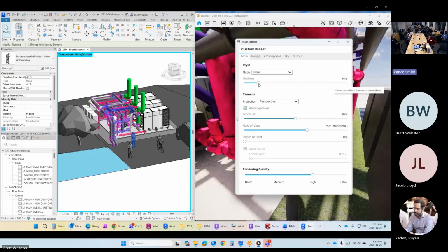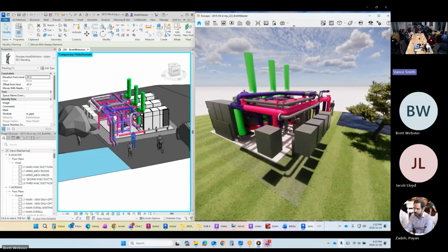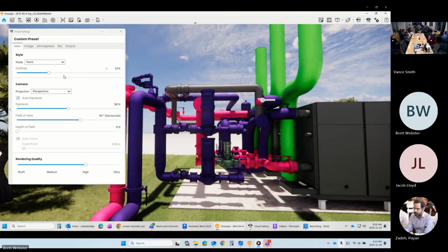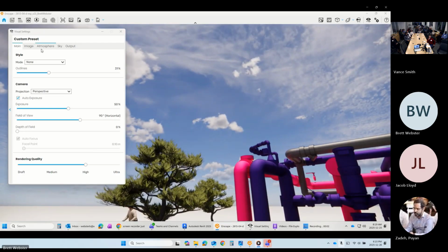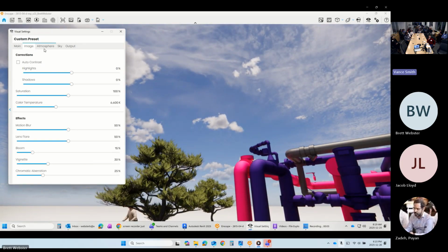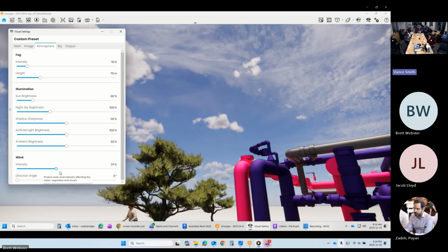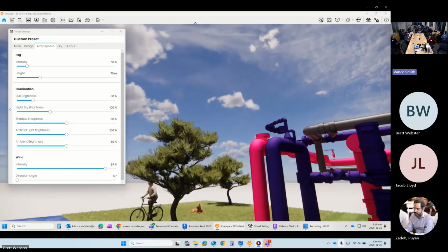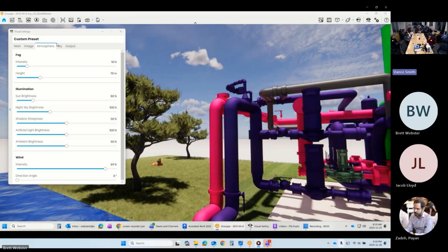So that's one of the atmospheric settings that you can do. Just scroll around in a second. Then you can look at the rest of your environment as well. So it's just going to flick over in a sec. The rest of the environment can also be controlled. There's all kinds of camera settings, image settings, but the atmosphere side of it is dealing with, well, you got wind intensity. So as you're scrolling around, you can make it windier so the trees will move more. And any other animated elements like the grass and the water will be affected by that.